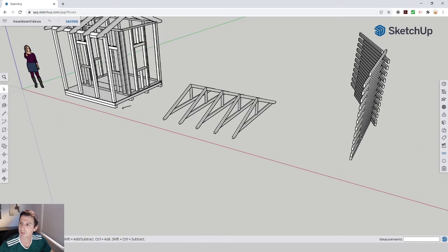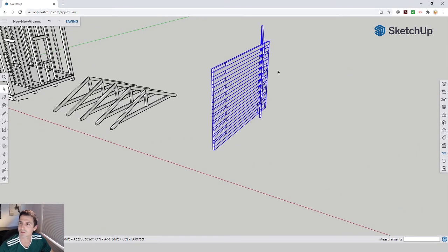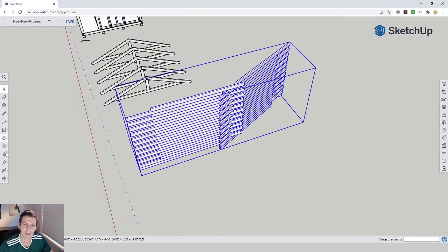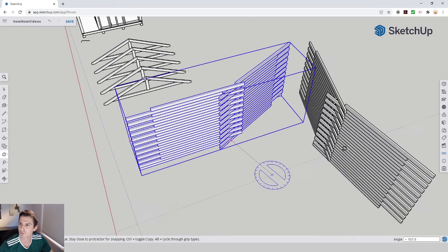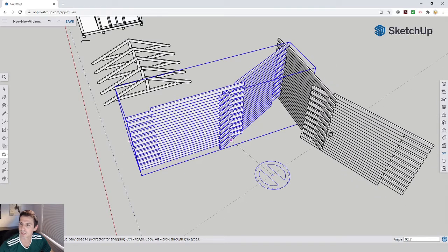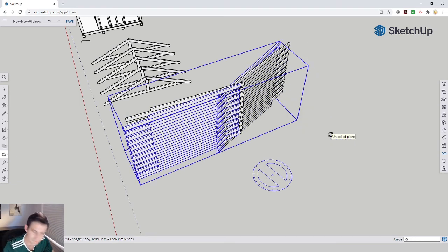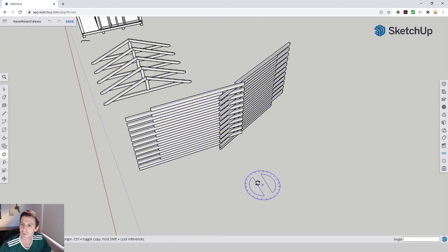You can do the same thing with copying and pasting a command like this. I'm going to turn this into its own group right now. I can use the rotate tool, and I can pick a center point and a start point, and I can tap Control and do the same thing. I can get 2 right here. I can then click and hit the star key once again to multiply that command and say I want 5 of those copies. And let's see if that can work a little bit better.